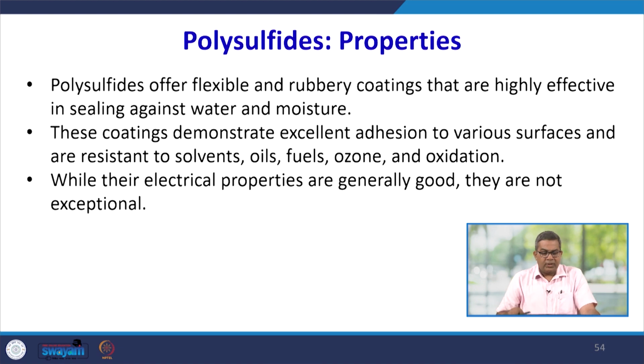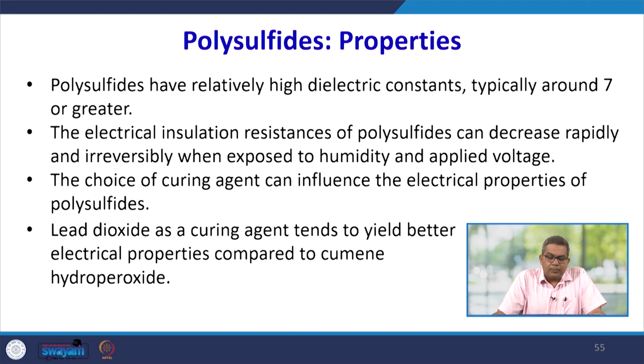Let's talk about the properties. The polysulfide offers flexible and rubbery coating, and they are highly effective in sealing against water and moisture. And these coatings demonstrate excellent adhesion to various surfaces and are resistant to solvent, oil, fuel, ozone, oxygen, etc. And their electrical properties are generally good. They are not exceptional. The polysulfide has a relatively high dielectric constant, typically around 7 or greater than 7.